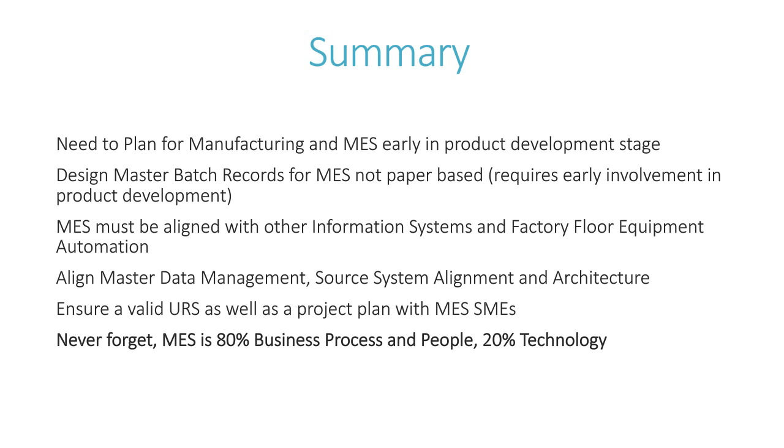Yeah. So a couple of assumptions. The first thing I wanted to say was that not all the information for the batch release is going to be in MES, right? You're going to have data in your deviation system, investigations, your LIMS system, for example. So your quality management system and LIMS are going to have information. But with regards to the batch record review itself, you could see a substantial reduction. I mean, I've seen 50 to 70% reductions in time to do a batch record review. But that's also assuming you've gotten people really acclimated using the MES the way it should be done. But you can see a significant reduction.